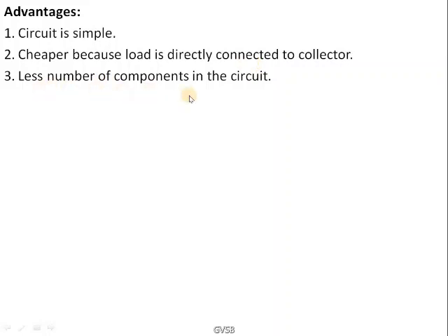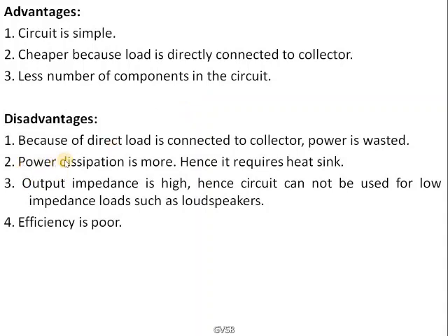Let us go to the disadvantages of series fed Class A power amplifier. If you see, because the load is directly connected to the collector circuit, more power is getting wasted. Power will be wasted in the form of heat. So definitely we have to use heat sinks. That is one more disadvantage.